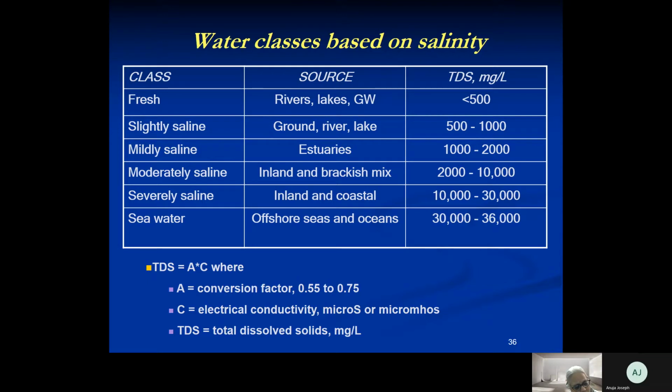So there is a small difference between TDS and electrical conductivity. But like I said, in drinking water samples, if they are good quality water to begin with, it's not a major issue. But if it is poor quality water or some other type of water, then you may have a serious problem in using this equation or in this approximation.